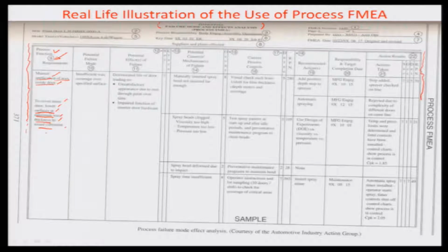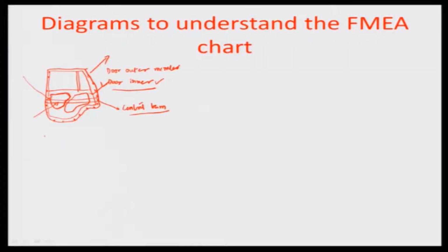So the purpose here is, obviously when you have made the door outside and the door inside, you are able to somehow go inside these gaps into the space between the door inside and outside, and are able to apply wax in these particular areas or regions, to ensure that if there is some kind of water splash, and obviously the door opens and closes many times, and it is quite accessible to the splashes of water, etc., which come out during the routine operations of the vehicle.